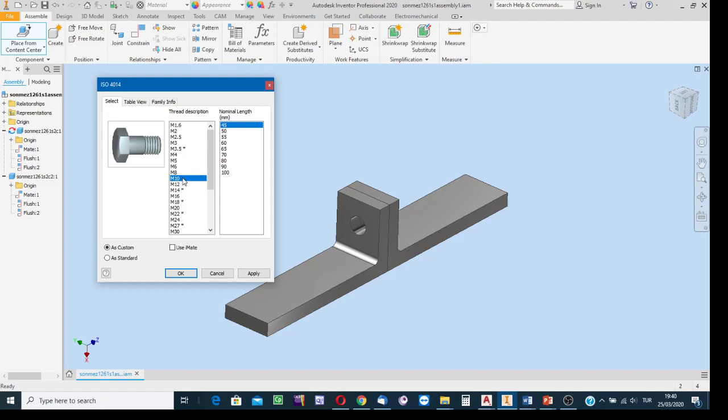Here, in the length field, well, this is a question to deal with. Okay, we said that the diameter of the bolt is 10, but in the other list, you see we have the length of the standard bolts. Saying nominal length of a bolt, we mean the length of the stem. The thickness of the head is not included. Well, what should be the value? How many millimeters? In the market, the minimum length is 45. Okay, the maximum length is 100 millimeters.